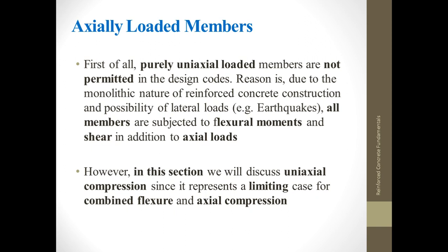Before we move on to the engineering formulas for solving axially loaded members, we need to know that purely uniaxial loading is not permitted in design codes. The reason for that is the monolithic nature of reinforced concrete construction, and of course the possibility of lateral loads.